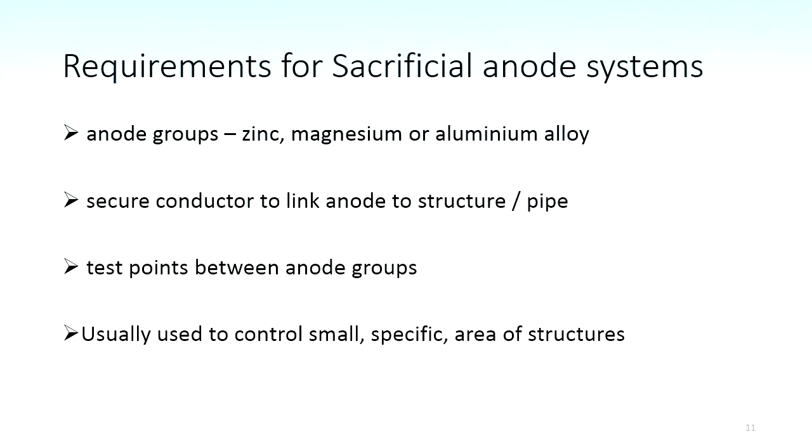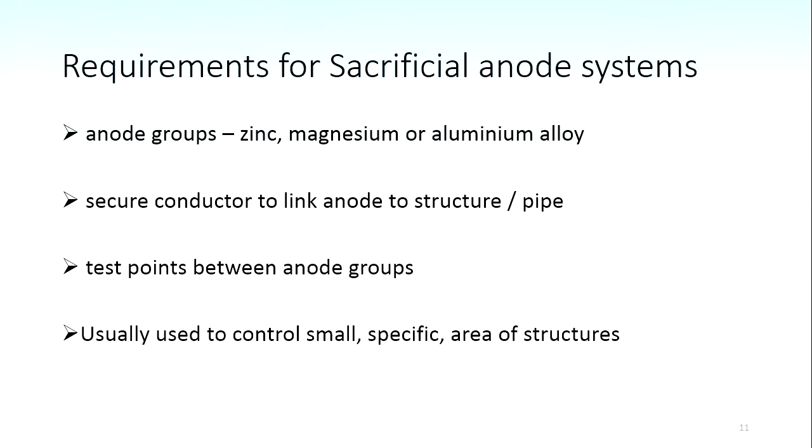When you move to E prime, then you're right. On this diagram, you've got about a 50-50 ratio of applied current to corrosion current. But you're actually trying to reduce the corrosion current. You want that to be small.